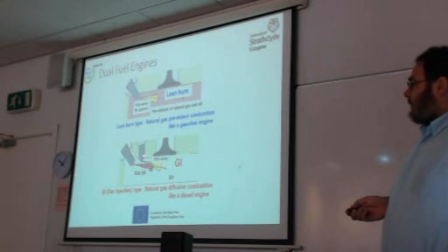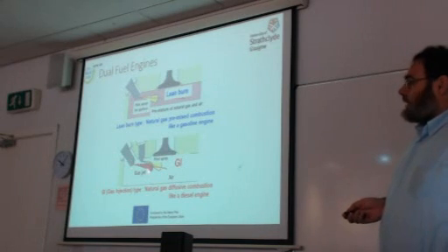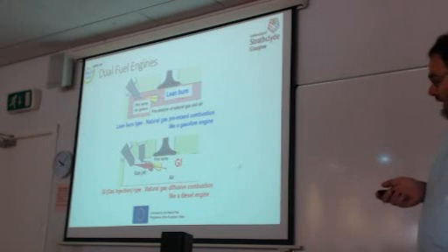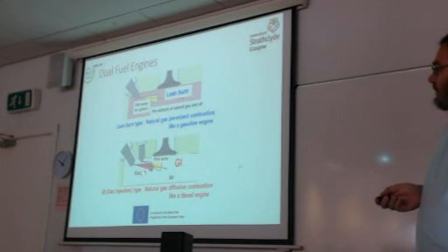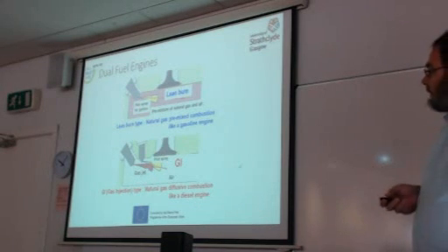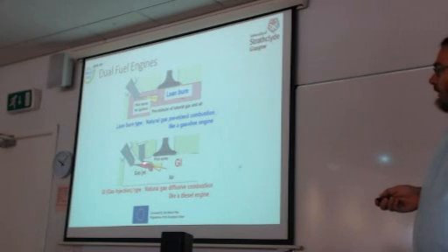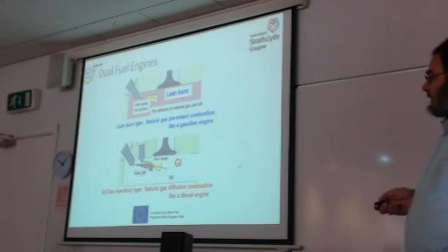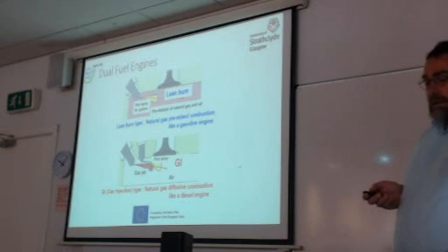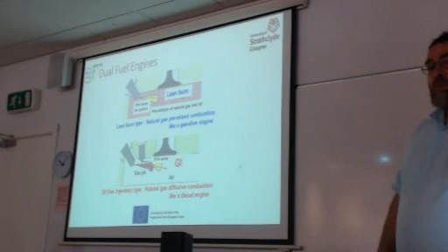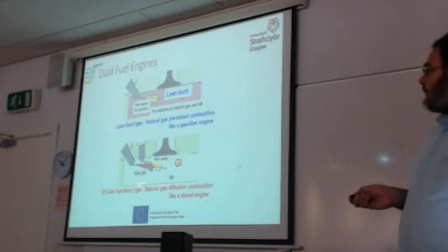And then in the gas ignition or gas diesel engines, we have the simultaneous injection of two jets of two fuels. So we have the pilot fuel and the gas fuel. In this case, as I will present in a later slide, combustion happens actually in parallel. So there is initiation of combustion from the pilot fuel, and then combustion is transferred to the gas jet.